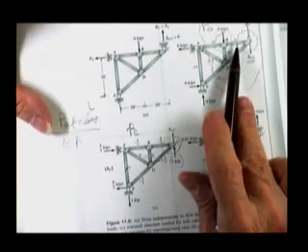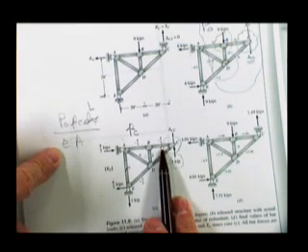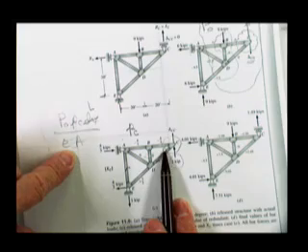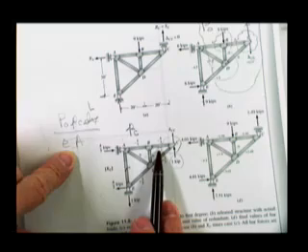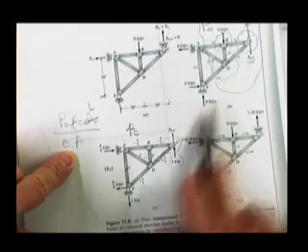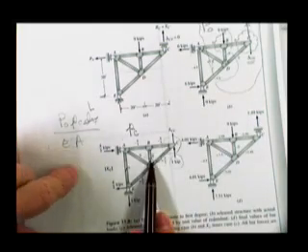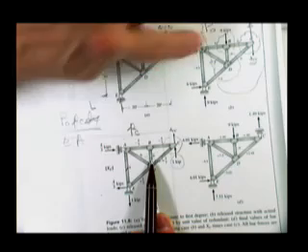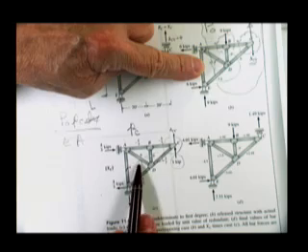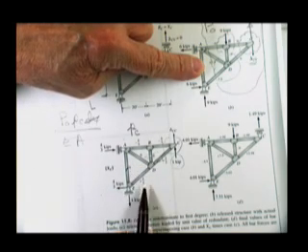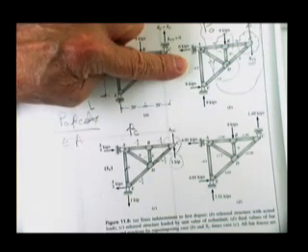And so you multiply 0 times a minus 4/3 times the length of that member divided by the E of that member divided by the A of that member, and that's a little piece of your final answer. And 0 times anything is 0. 0 times 5/3 is 0. Minus 9 times 0 is 0. We're not getting much here. 0 on this one times 4/3 on this one. 7.5 on that one, and times 0 on this one. 0 on this one, and 4.5. I haven't got anything yet. Maybe there's no deflection at all.